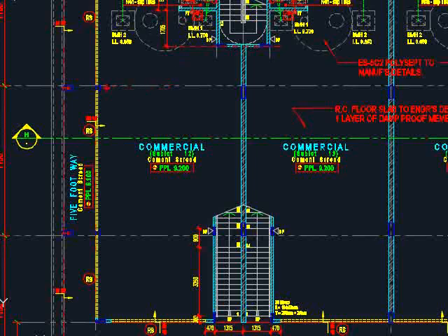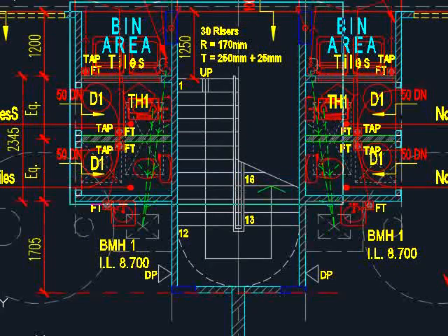You will have to come up with your own solutions to overcome this. It is either for you to reduce the size of the slab so that less stress is distributed to the beam, or you will need to enlarge the size of the beam and make sure it is high under the ceiling.